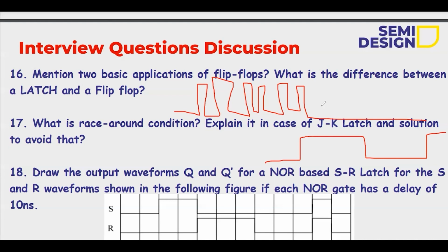That's why we move to the flip-flop, which is edge triggered. Edge triggering means only at the particular edge of the clock, whether the positive edge or the negative edge, the output will change with respect to the input. So latches are not mostly preferred due to this disadvantage. And for latches we also face race around conditions.